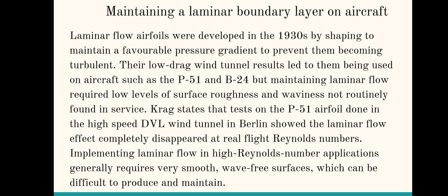Maintaining a laminar boundary layer on aircraft. Laminar flow airfoils were developed in the 1930s by shaping to maintain a favorable pressure gradient to prevent them becoming turbulent. Their low drag wind tunnel results led to them being used on aircraft such as the P-51 and B-24, but maintaining laminar flow required low levels of surface roughness and waviness, not routinely found in service.